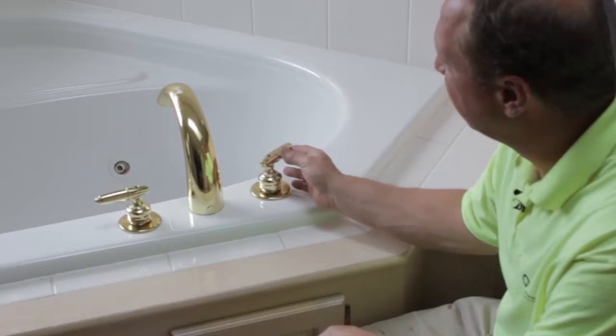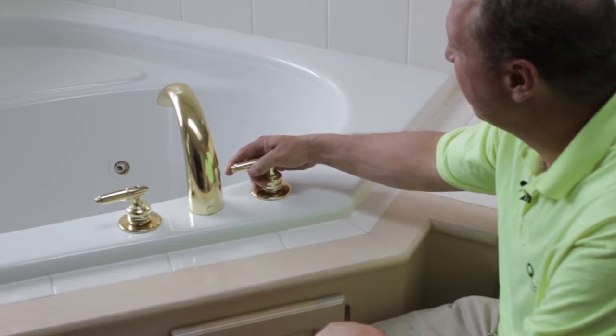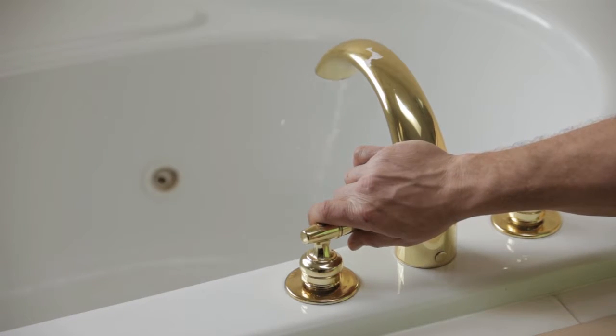Once charged, open the faucet or valve furthest and/or highest from the compressor hookup. Each faucet or valve should be opened one at a time and then closed prior to moving on to the next one to ensure full pressure at each fixture.